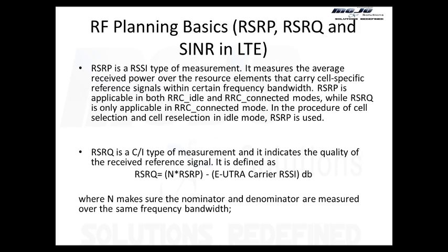In RF engineering and electrical engineering, instead of dealing directly with watts, we always use dBm, which is a measurement of power, and watts and dBm are interchangeable. You'll find a lot of calculators online, like how much dBm is 40 watts, and how many watts is 43 dBm. There's a mathematical formula, and there are a lot of calculators and tables available online.